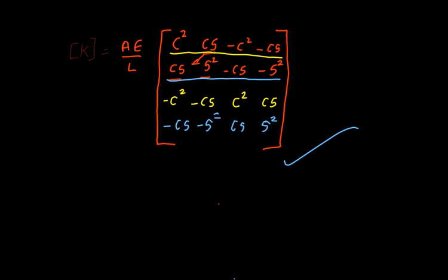Also, the important thing that you have to remember is when you have a truss member, and this is nodal point 1, nodal point 2, always mention the theta in the anticlockwise direction, that too from the least nodal points. Suppose now this is nodal point 1, this is nodal point 2. So what is the value of theta here? It's 0.